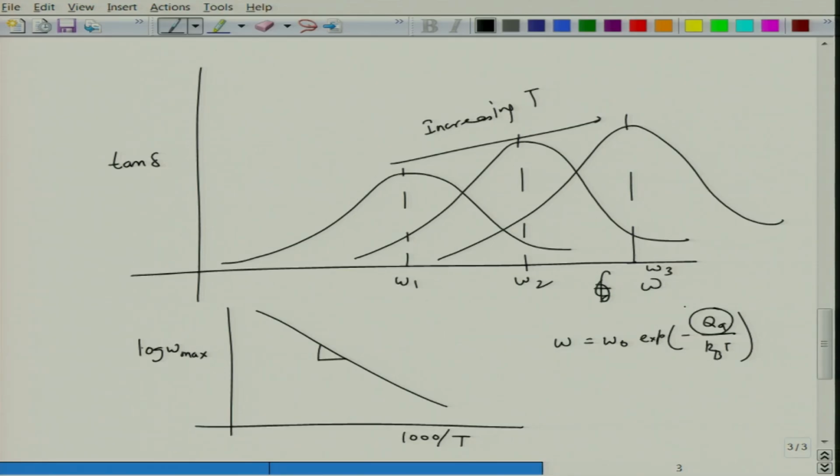Temperature dependent measurements of dielectric materials are a very useful way to understand the intricacies of dielectric materials, the activation energy, what kind of defects you might have, because these activation energies are a signature of what kind of defects and processes are present in the materials. So, one can make very nice conclusions about what happens in various different kinds of materials.